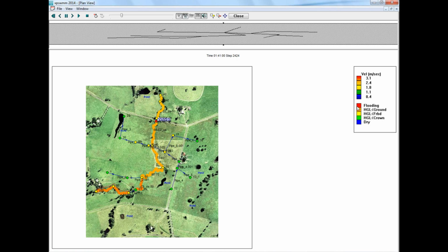There's a red flooding indicator down towards the downstream end of that water course that Ludmilla shared with you earlier. And notice this kind of white wiggly blue indicator. This is the flood indicator. So this is telling you this is where the flooding takes place. You can see flow coming through the drainage network and feeding into the channels at a variety of nodes. I'll close this view because it's showing you the 1D and concentrating on that, which I'm really interested in.